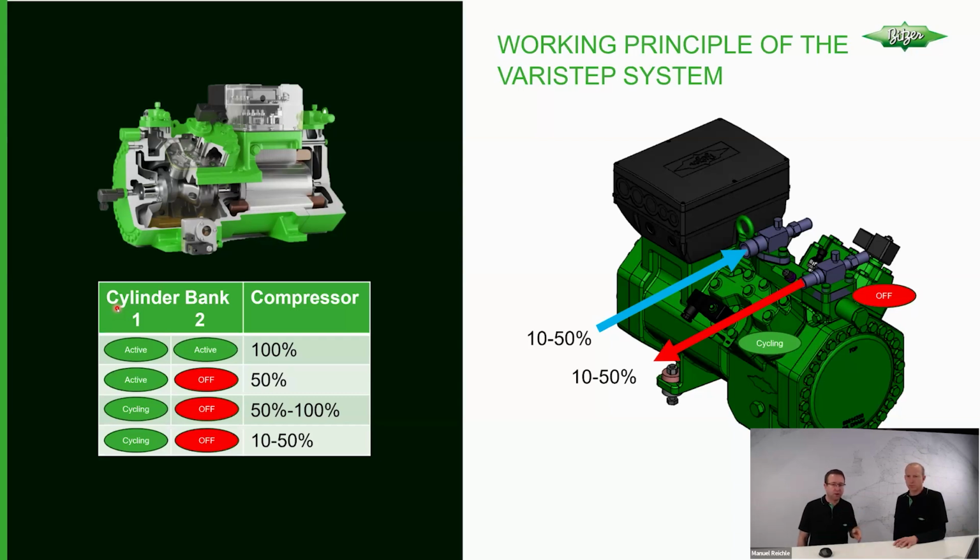I need to stop either this compressor, if it's the only one which is active, or if we have a compound system, it stops compressor number 2. Compressor number 1 will automatically run then at 80, 90, or 100%, and gets the full mass flow, is cooling down again. Everything is fine. We don't create any alarm or any unnecessary stop of the compressor.